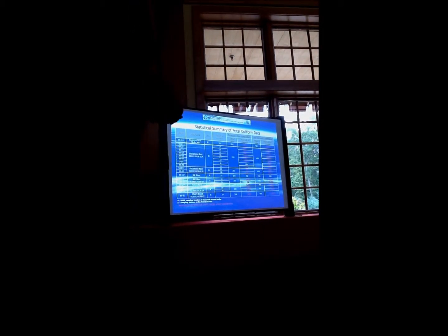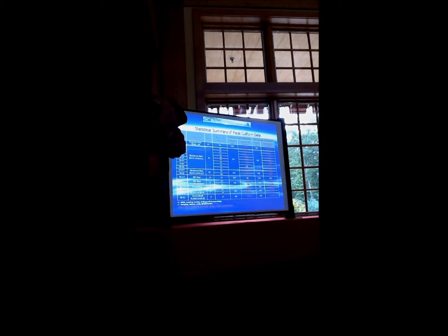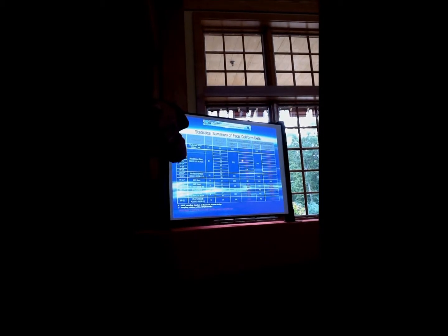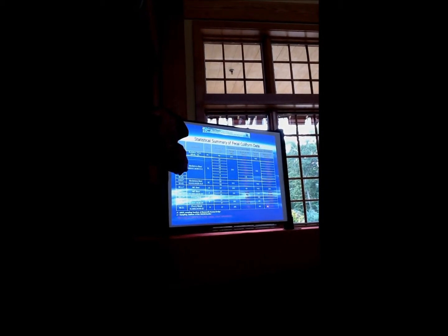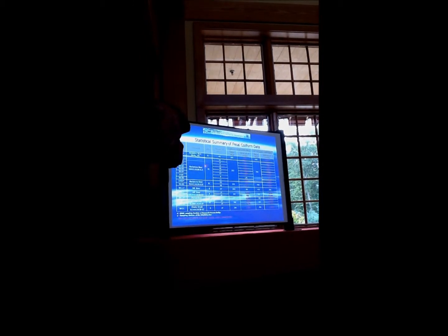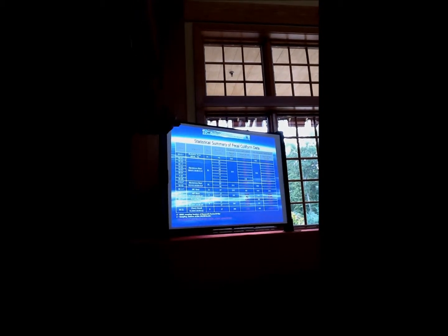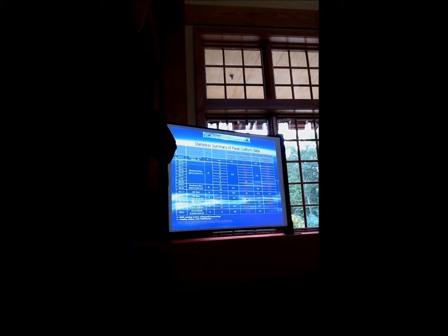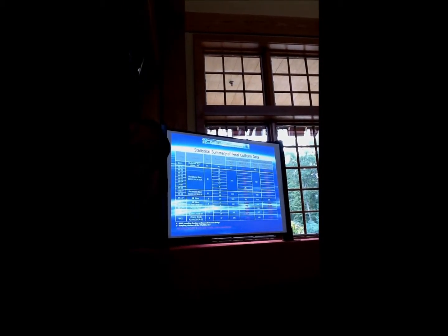This is a busy slide, but what I want you to take away from this, if you look at it, here are all our stations that we had. This is the water quality fecal coliform data. And all samples, all reaches, all stations violated or exceeded the water quality limit for fresh water, in all reaches except where Mill River comes across the state line. That was the only station that didn't exceed our water quality standard.